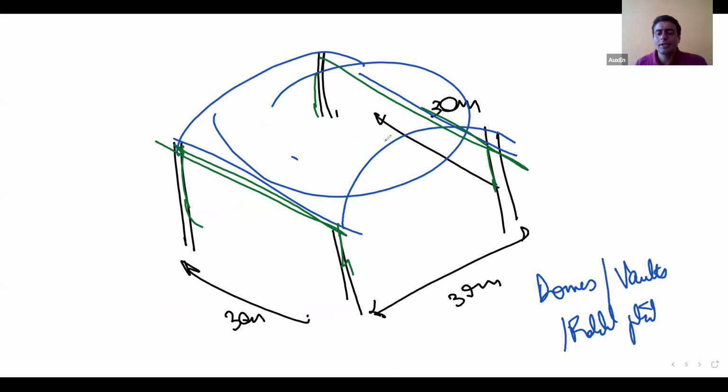Suppose I had a dome like structure. What are the predominant actions in this type of structural system or this type of arrangement? What are the dominant actions? So in this case, flexure does not remain a dominant action because of the configuration that we come up with. So dominant actions may become your compression, arch forces. Okay, is it clear?